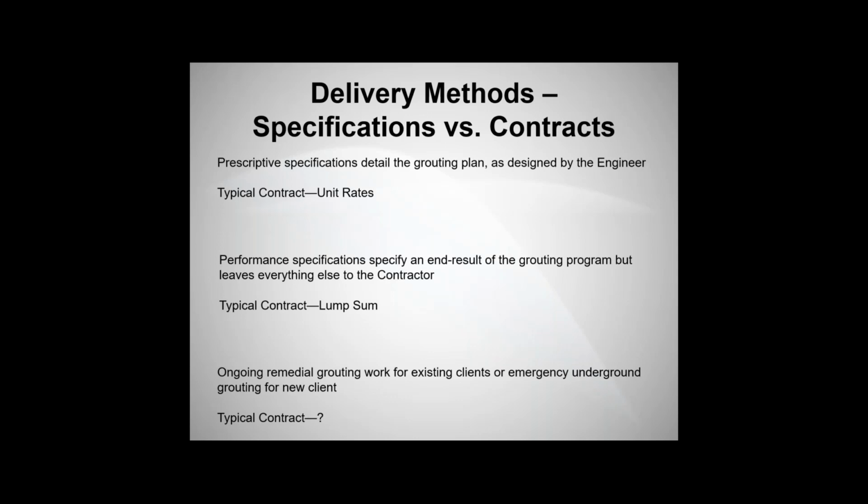Another way grouting programs are handled is when emergency work occurs. If you're mining along and you have a groundwater inflow into your tunnel or shaft and the general contractor can't deal with it, then a grouting contractor will come in and address the issue. Typically, these are paid for on a time and material basis. Even though I've broken these up into three different categories, it doesn't mean you can't have different payment types for different types of specifications. You can have prescriptive specifications that are paid for on a time and material basis, but generally this is how everything is broken down.